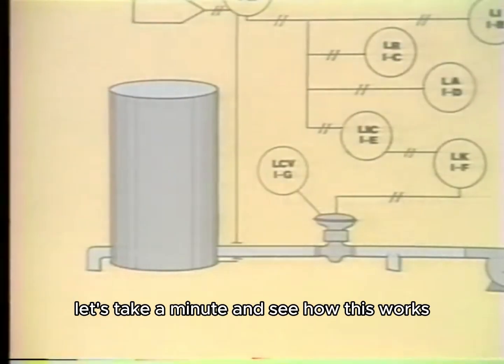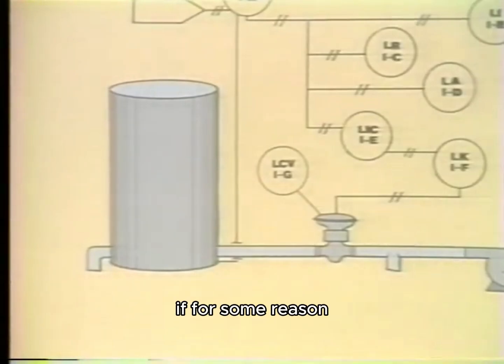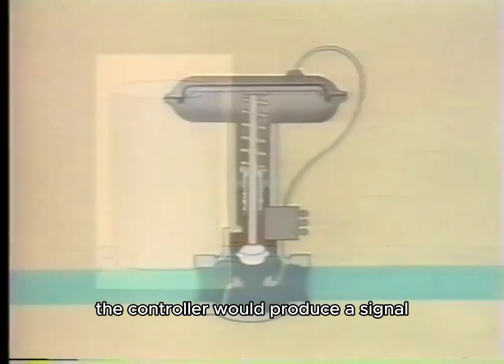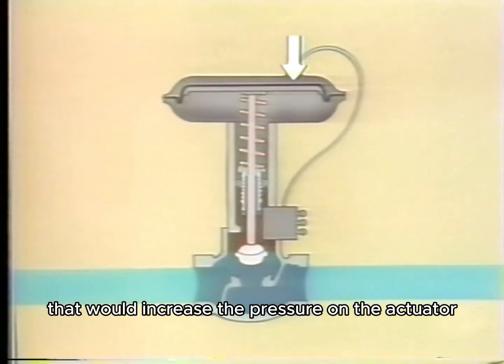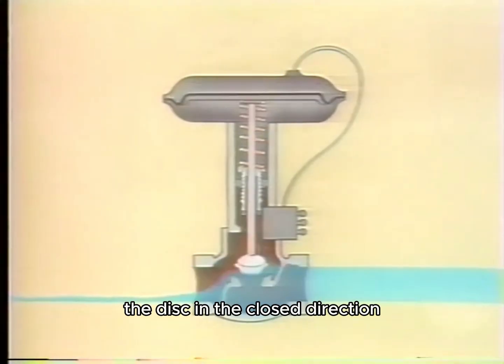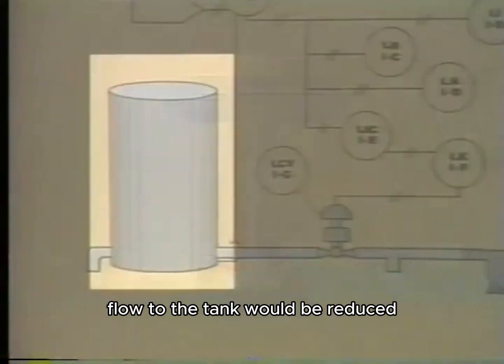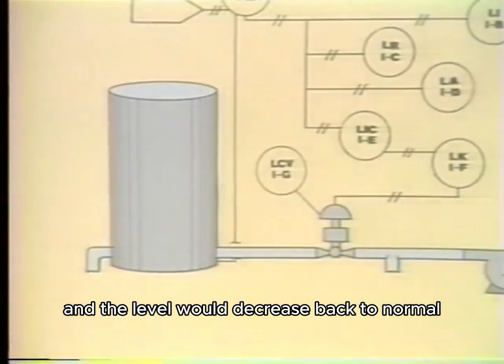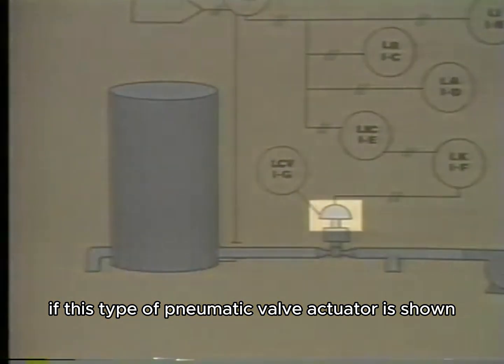Let's take a minute and see how this works. If for some reason the level in this tank began to increase, the controller would produce a signal that would increase the pressure on the actuator. This would cause the stem of the valve to move the disc in the closed direction. Flow to the tank would be reduced and the level would decrease back to normal. If this type of pneumatic valve actuator is shown on a P&ID, it would be symbolized like this.